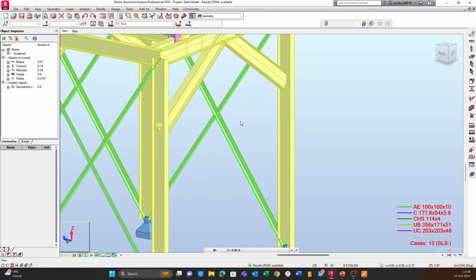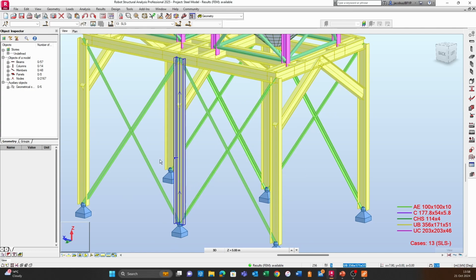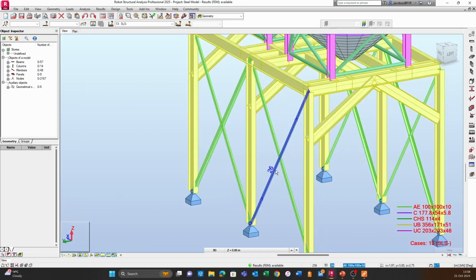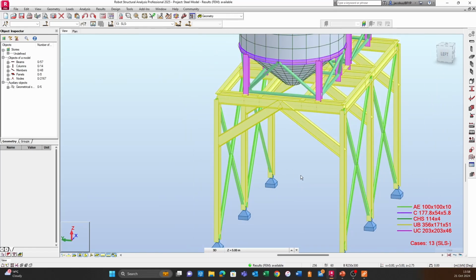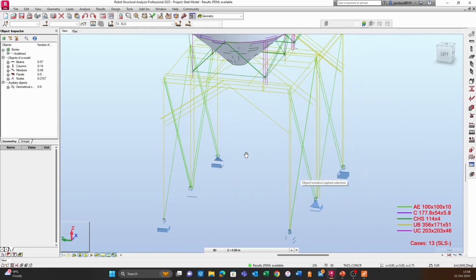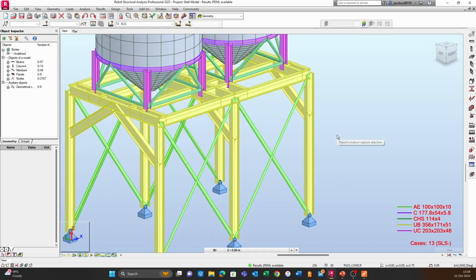Look at how your members are orientated, specifically how they're rotated about their longitudinal axis. That is very important because it is a detail that is taken up into Checkbot, and it forms part of your connection when you proceed to connection design. It's not something you can change within the IDEA StatiCa space if using the Checkbot workflow.